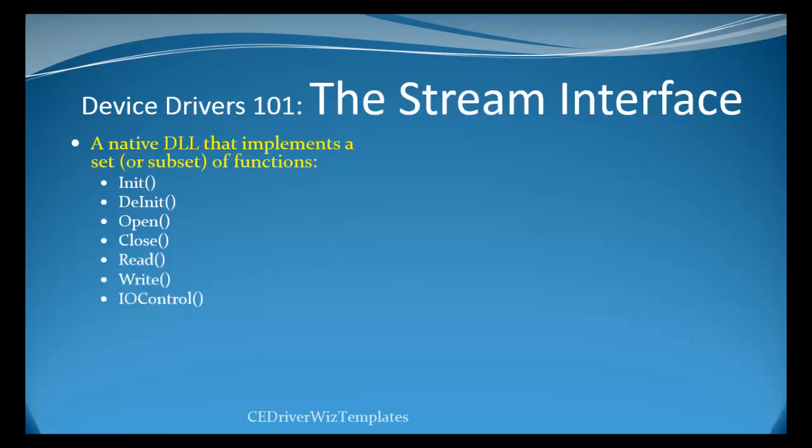To actually move data in and out of the stream driver and to do lower level controls and also do data movement, there are the functions read, write, seek and IO control. IO control uses what are called ioctls. There are some of these functions that are optional, in particular the power up and power down functions, which can be implemented. Generally though, you might find that power is actually implemented as an interface through the IO control function.